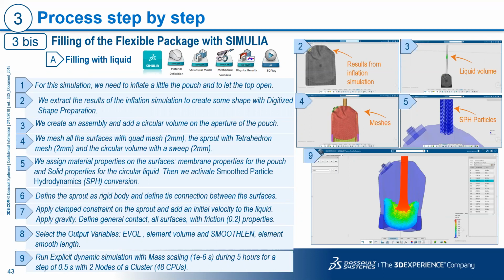If you want to capture all the physics, you want to go with a fully coupled fluid structure interaction approach. If you want to do it much more cheaply, then depending on the complexity of the problem, you can go with either the hydrostatic fluid or the SPH approach. SPH, I would say, is a good trade-off from going for the more expensive Eulerian techniques or a fully integrated approach.